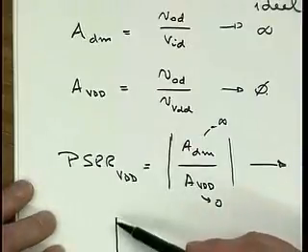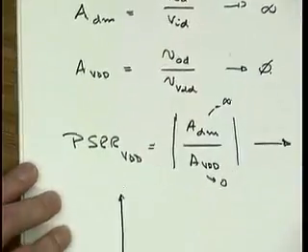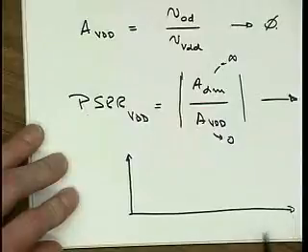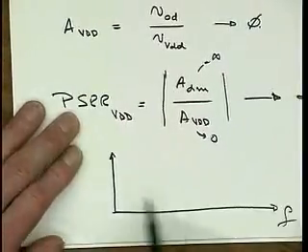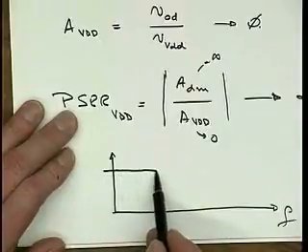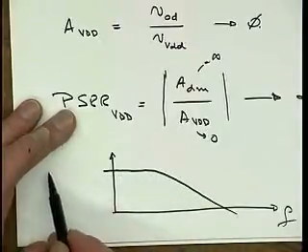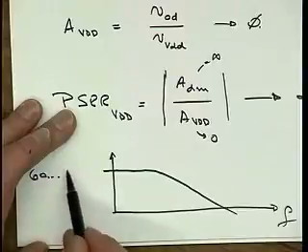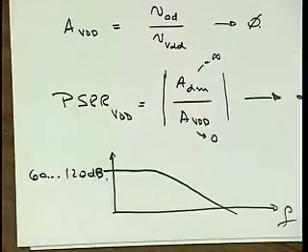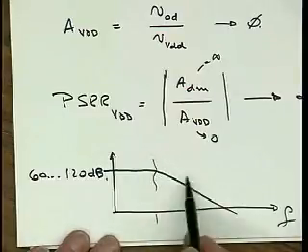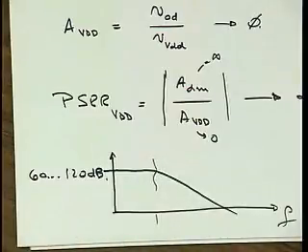And typically, it's a function of frequency, and we've seen that already in the context of references, where the power supply, of course, is also an undesired input. Usually it's going to look something like this. And if you're good, then this may be 60 to 120 dB here. And then at some point it rolls off, and it's not so good anymore. Differential circuits help a lot here also, because we'll see that better when we design them.